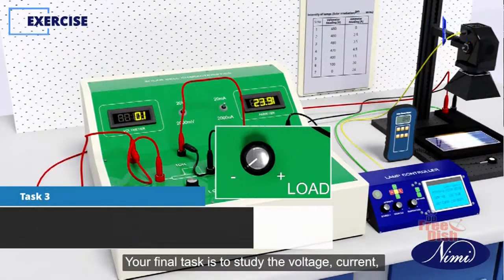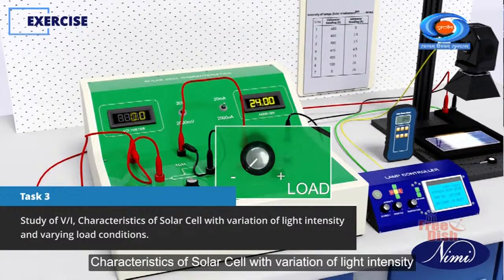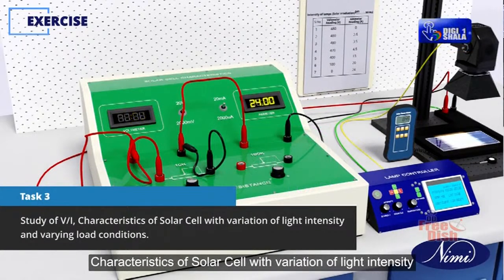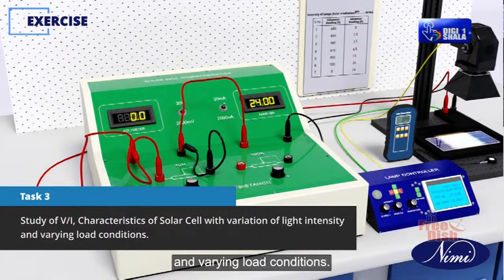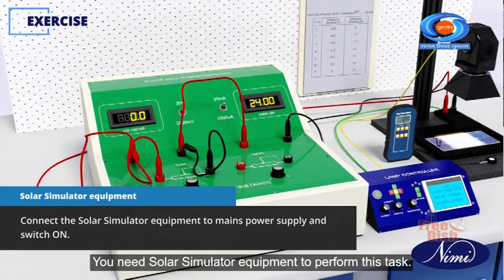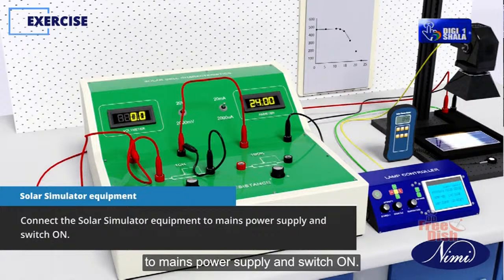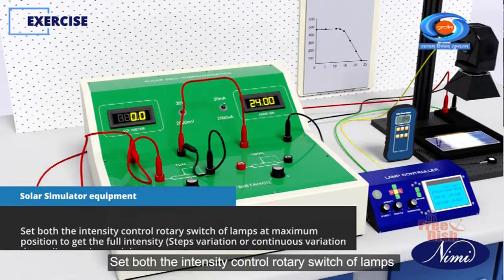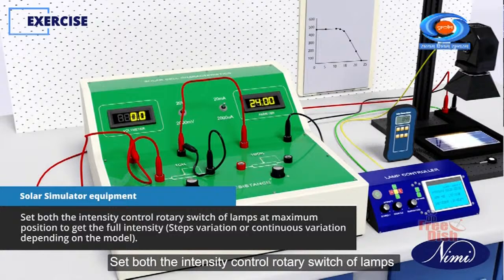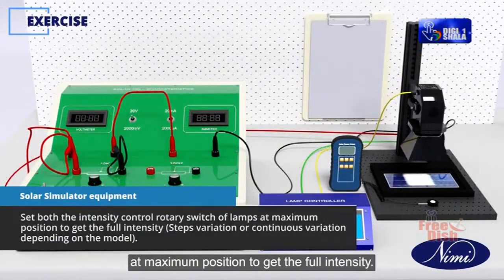Your final task is to study the voltage-current characteristics of a solar cell with variation of light intensity and varying load conditions. You need solar simulator equipment to perform this task. Connect the solar simulator equipment to the mains power supply and switch on. Set both the intensity control rotary switches of the lamps at maximum position to get the full intensity.